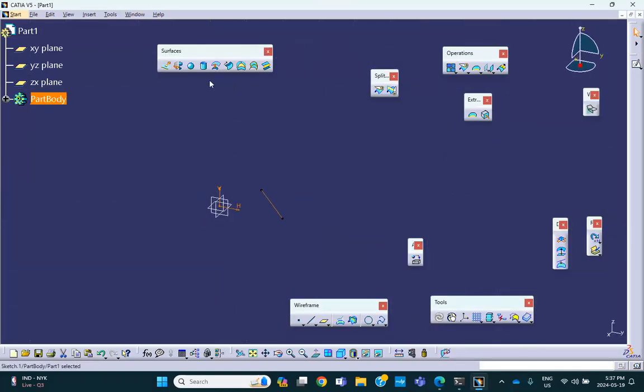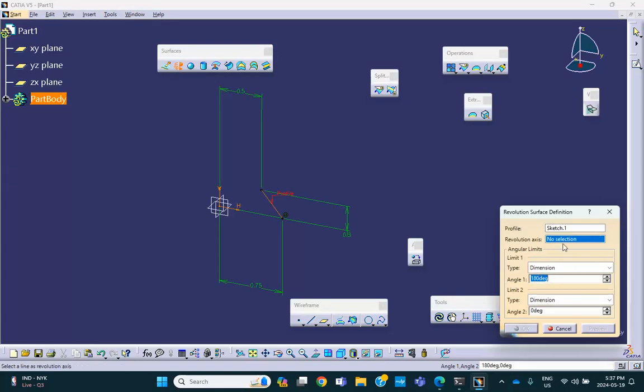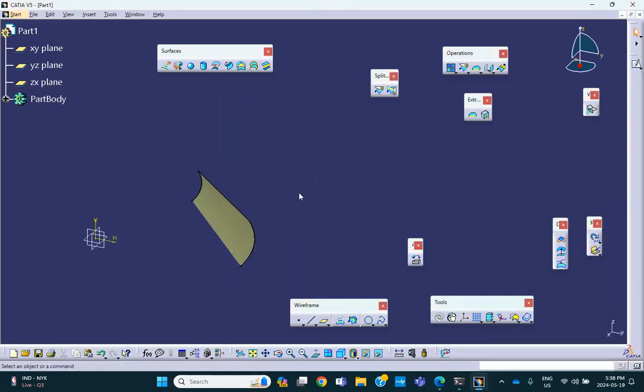Exit, and then revolve it. Here is revolve, on the surfaces. About the z-axis, but by 40 degrees. So I'll put down 40 here. Very good. So this is what we got. Now notice that there's a sketch here. I'll leave it there. I can hide it, or I'll leave it here to show you what happens when I leave it there. The other thing is that this edge, where I did my sketch, is in the YZ plane, and the other edge is not in any one of these three planes.